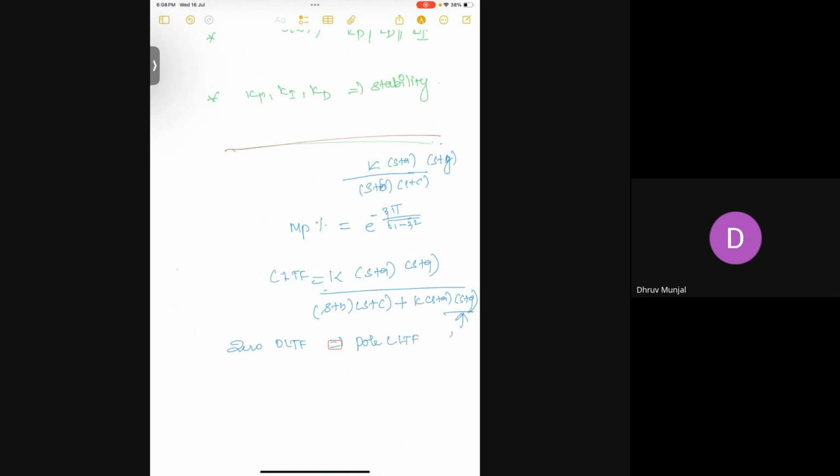So this contributes to stability. So far, we will be seeing only the poles' nature for stability, but we ignore the location of the zero while measuring the stability nature of a system. But an open loop zero will become poles in the closed loop transfer function.